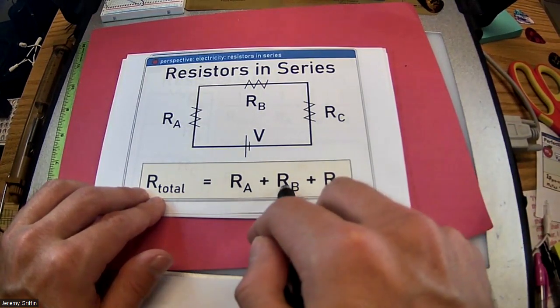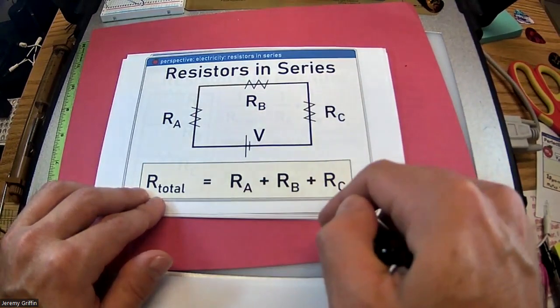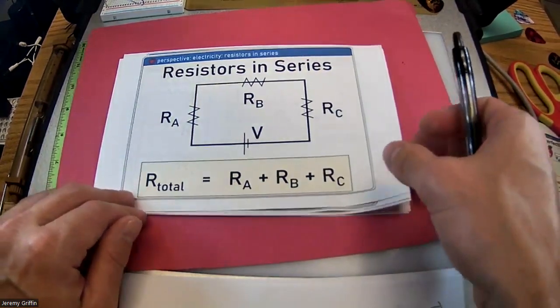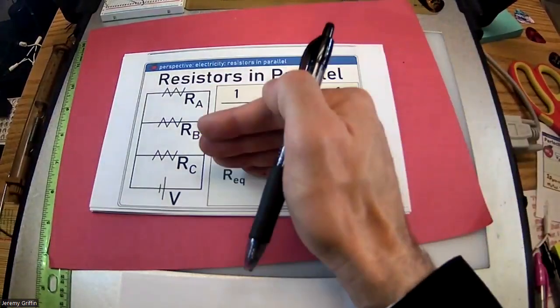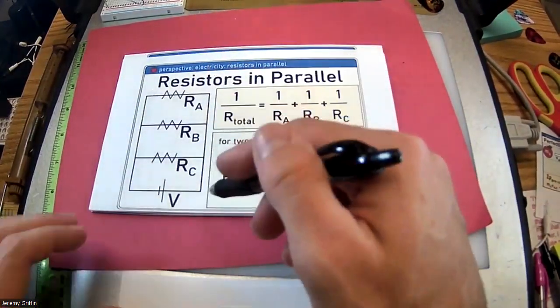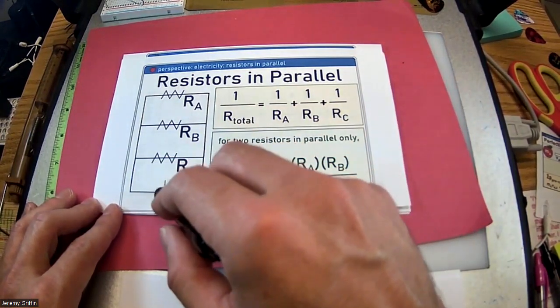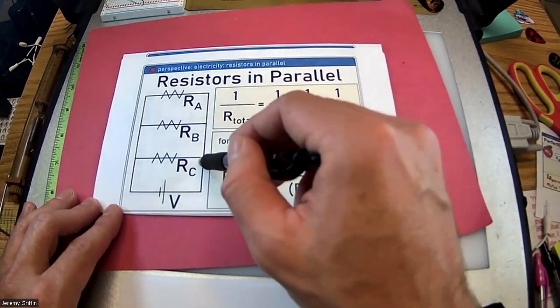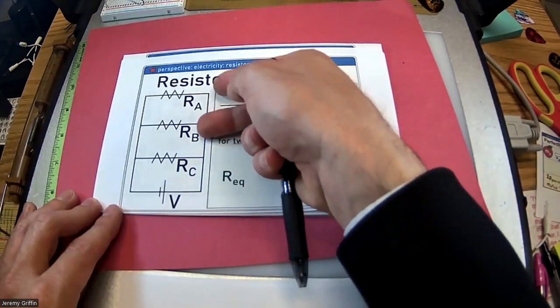Right? And every time you add on a resistor in series, just one after another sequentially, you can very simply add the resistances to get the equivalent resistance. Right? But then he switched and wired them like rungs of a ladder, which is in parallel. And this is where the current splits. So here comes the current flowing around. And oh, I see a junction right here. So the current has a split. Current right here splits. Right?